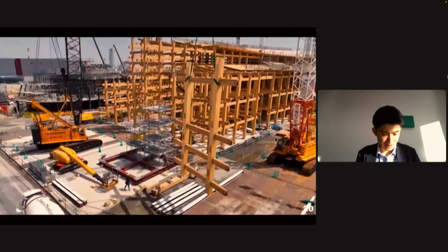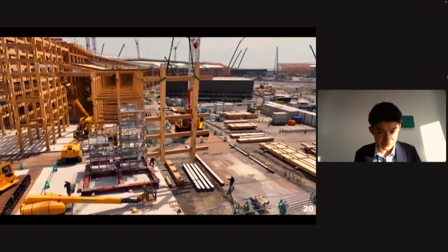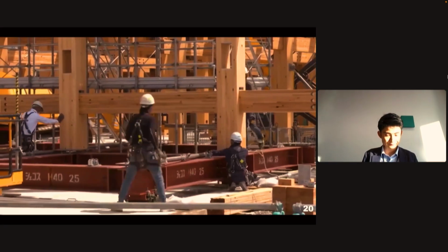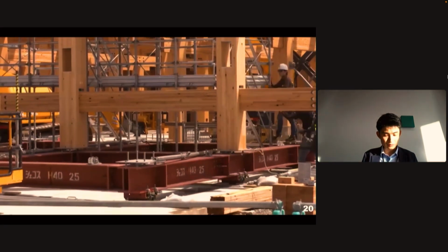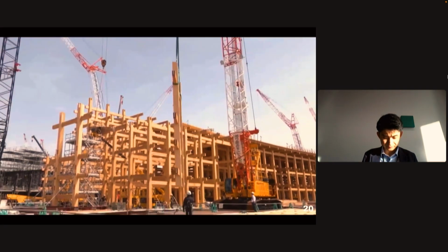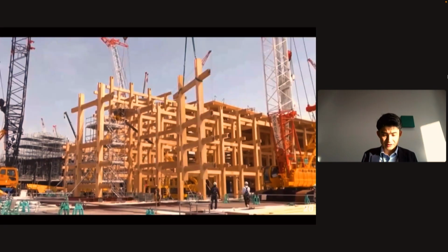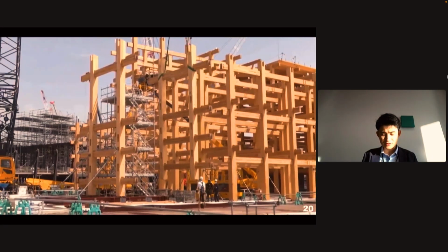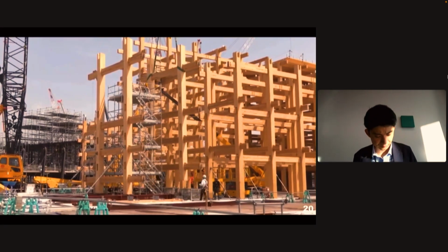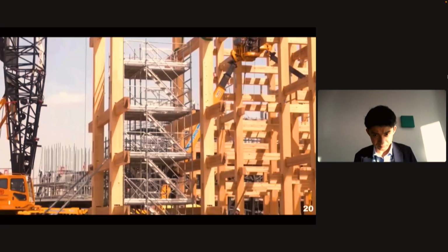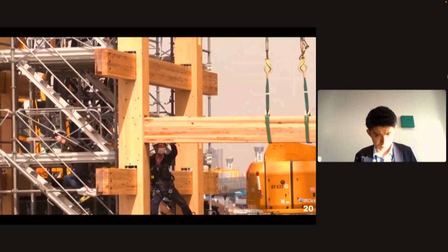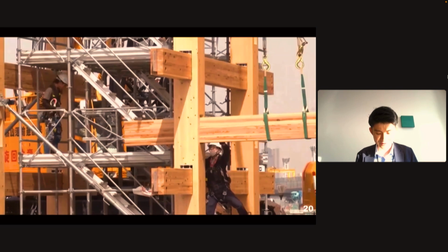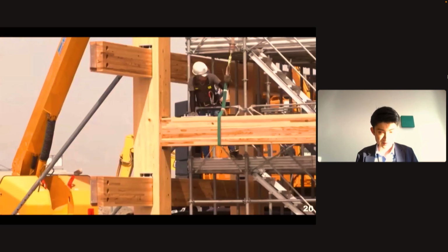And next is the upper structure. With safety first, we assemble as much as possible on the ground. Again, we start with planar units. Even when geometry is large, the principle is the same. Keep operation repeatable. And pass the beams to form a stable 3D frame, and then lift it.